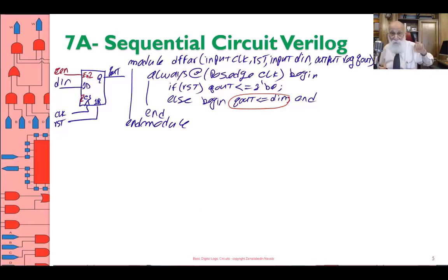Okay, but now I'm adding another condition, which is: if the reset is there, reset it. But if the reset is not there, then look to see if clock enable is 1. Only then do this red thing here. And therefore, what I do is after the else, I put if, to make it fit in this area. Sorry, I had to use dark red to correspond to that thing, or brown.